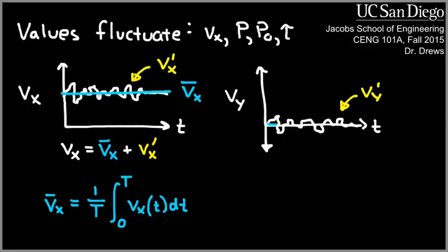There is an average vy for the way that we drew this before. It just so happens that vy bar will be equal to 0, because on the whole, for fully developed flow, there is no bulk motion in the y direction. But there is a component of the random noise signal, the fluctuating signal, v sub y prime, that does have to be taken into account. And so when I say, what does that mean? How do we take something like that into account? What we're going to look at is the effect of these fluctuations on the momentum balance.